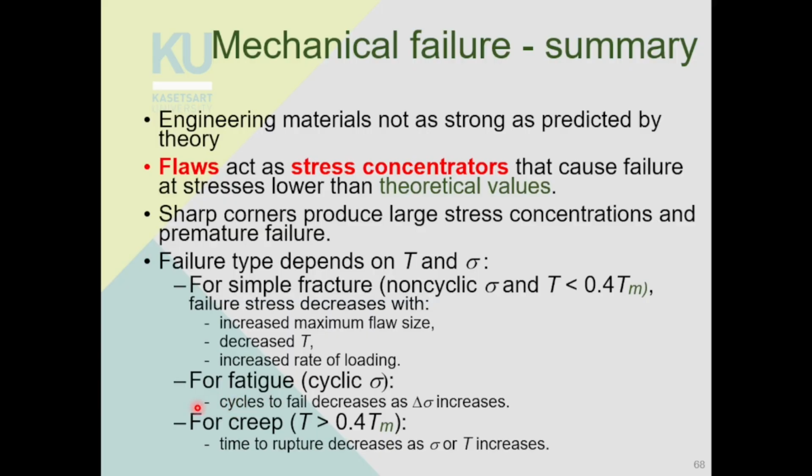For fatigue, so cyclic stress, fluctuating or dynamic stress, cycles to failure decreases as stress amplitude increases. For creep, constant stress at temperature above 0.4 Tm, time to rupture decreases as you increase the stress or increase the temperature.